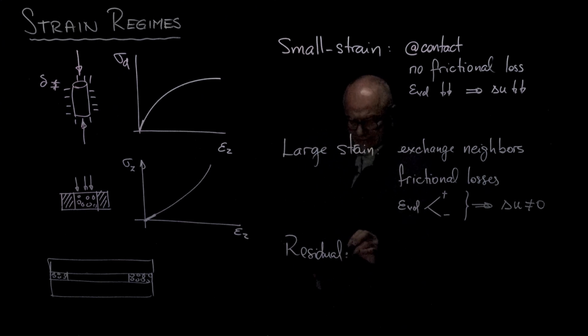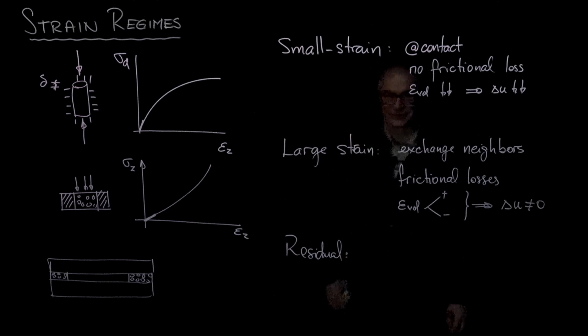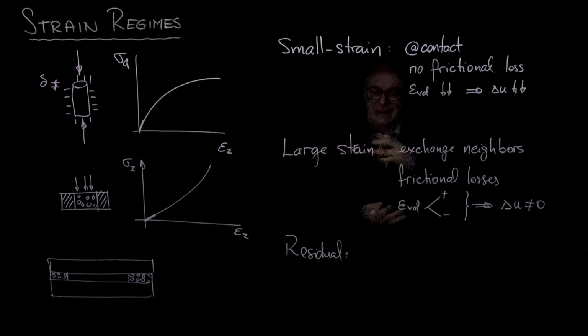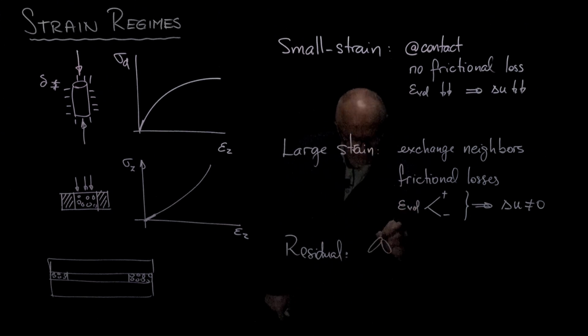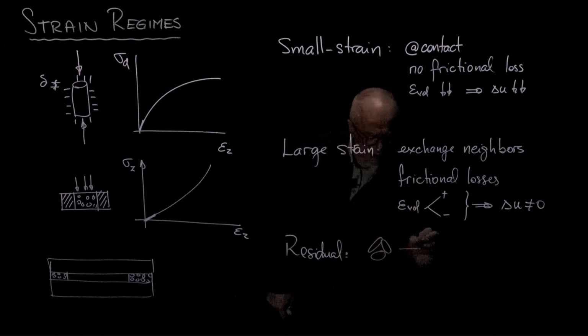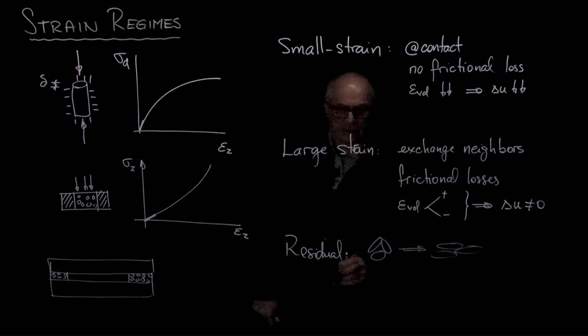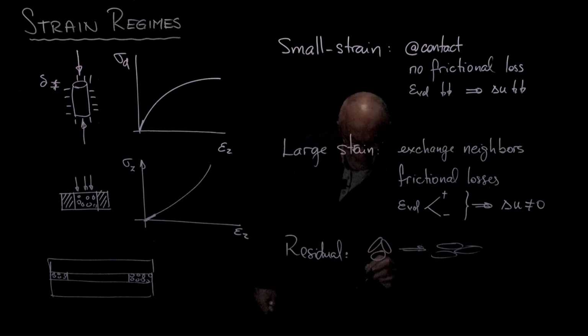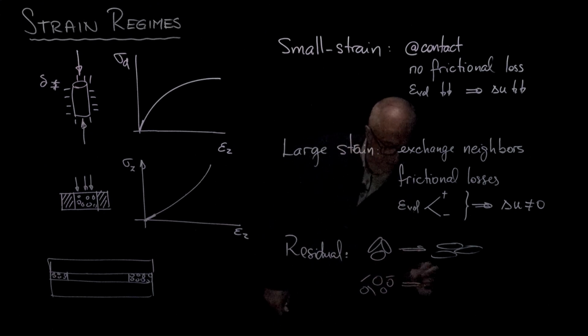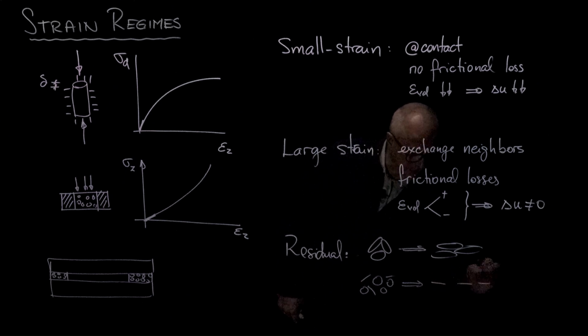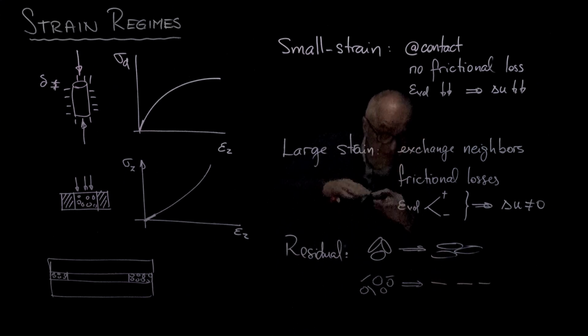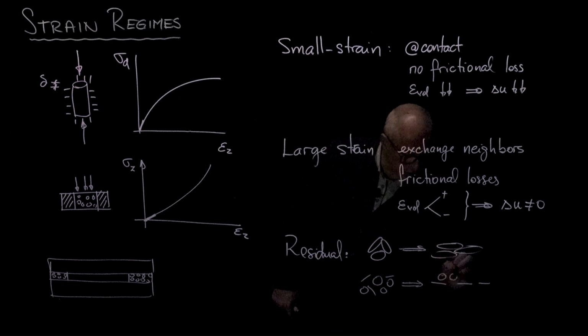Finally, in the residual regime, when the system has deformed a lot, many things happen. For example, elliptical eccentric particles become aligned. If you have mica in sands, the mica platelets were surrounded by grains, and now the mica platelets segregate and they tend to form like a mirror surface, a polished surface on which the coarser particles ride.